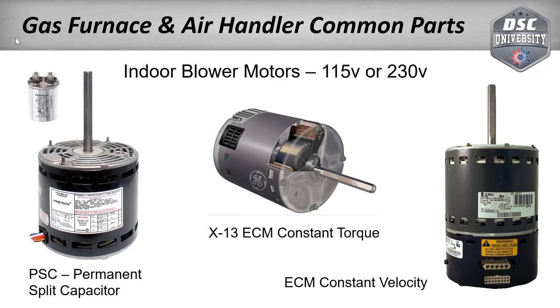As of July of last year, one of the federal regulations went into place so that manufacturers can no longer build gas furnaces with PSC blower motors. So that's why you're seeing new model numbers on the gas furnaces, because now all of our gas furnaces are going to have either the second or the third type of motor. The second type of motor is the X13 ECM constant torque motor. Just like everything else with the government regulations, the X13 ECM motor is more efficient. Of course, it's also more expensive. So that takes our gas furnaces and adds a couple of $100 to the price of them or so, depending on sizes and all that.